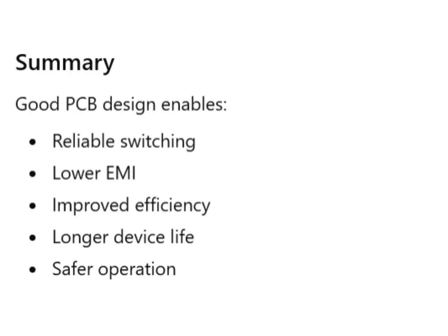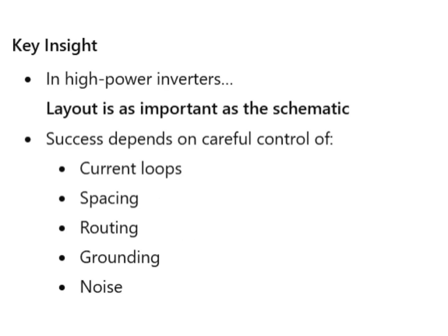Summary. Good PCB design ensures reliable switching, lower electromagnetic interference, improved efficiency, longer device life, and safer operation. In high-power inverter systems, layout is just as important as the schematic. Careful attention to current loops, spacing, routing, grounding, and noise control is essential for successful hardware implementation.